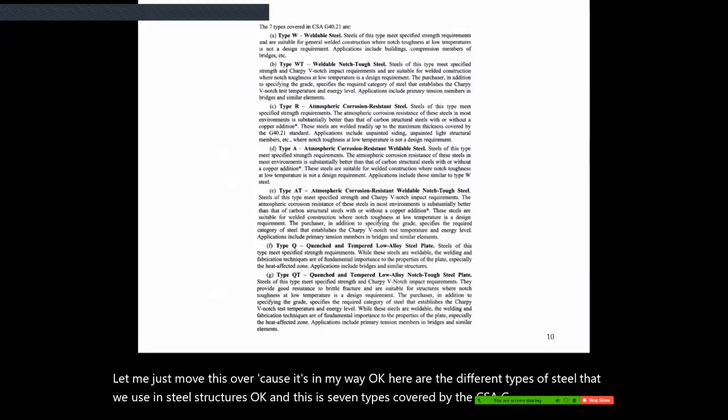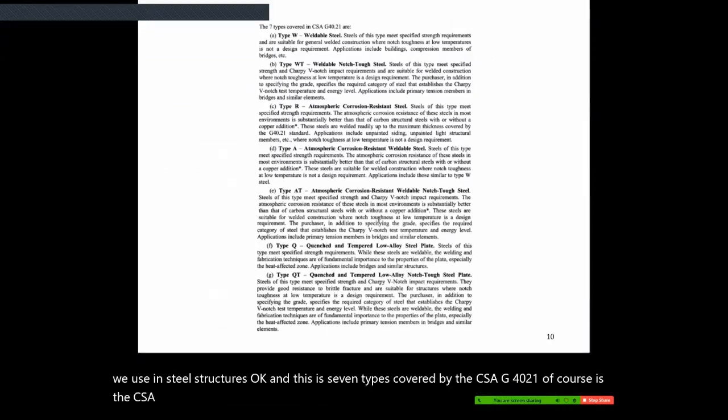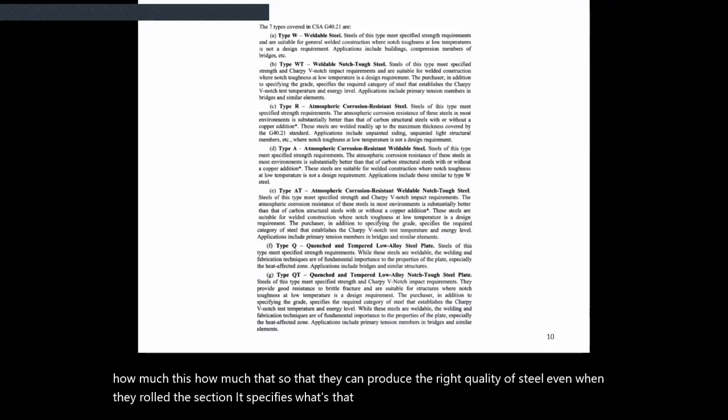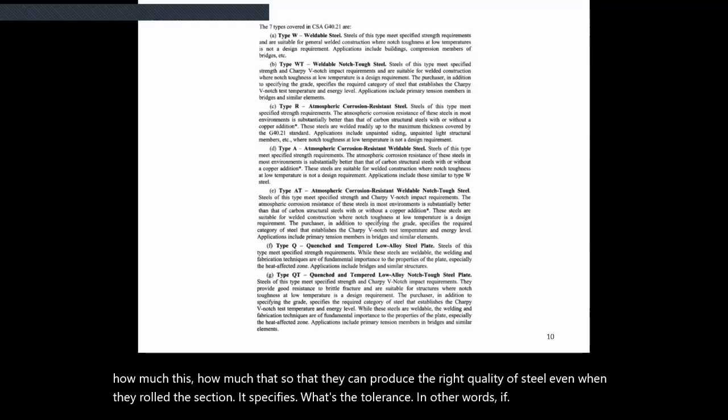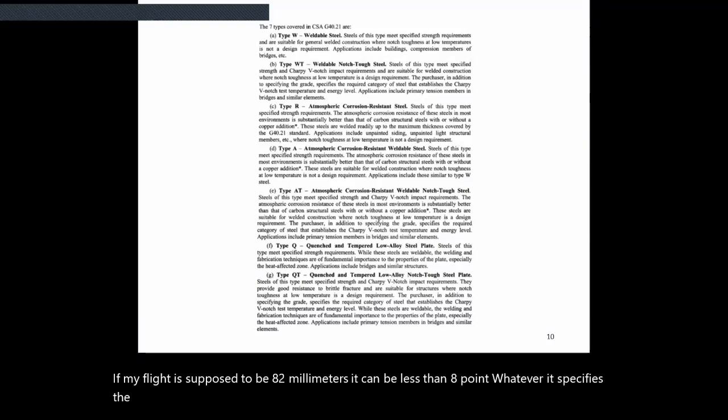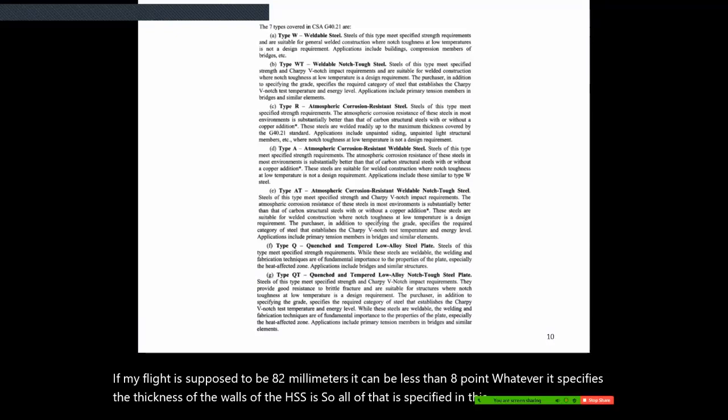Of course, this is the CSA standard that will tell the mill how much carbon, how much iron, how much nickel, how much this, how much that, so that they can produce the right quality of steel. Even when they roll the section, it specifies the tolerance. In other words, if my flange is supposed to be 8.2 millimeters, it can't be less than 8 point whatever. It specifies the thicknesses of the walls of the HSSs. So all of that is specified in this standard, CSA G40.21.